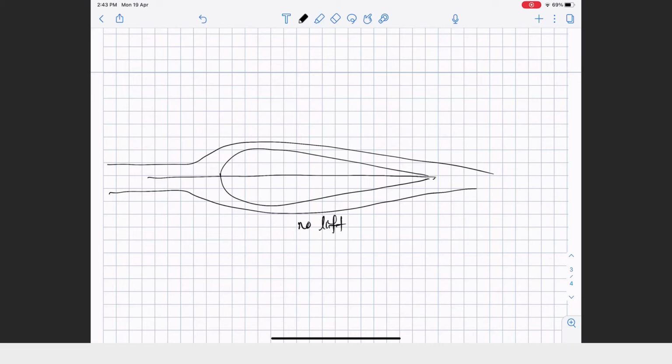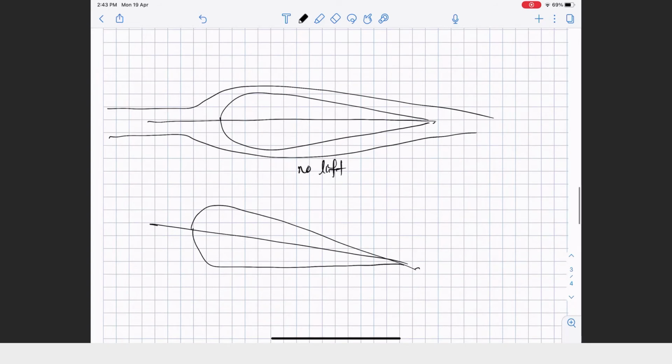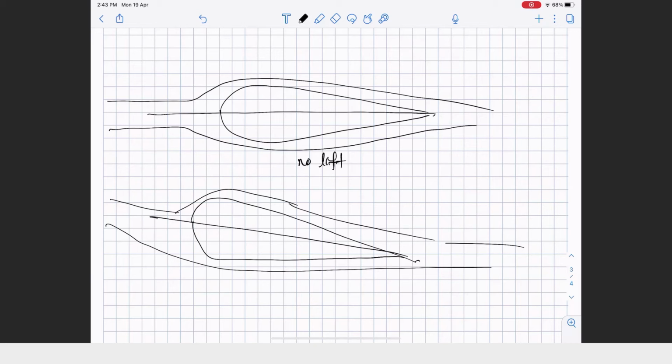It's not so interesting, is it? So what we will do is give the aerofoil an angle of attack. Angle of attack means that now your aerofoil looks something like this. Now I believe you can tell that this aerofoil is generating some kind of lift, because there's a difference between the streamline above and the streamline below the aerofoil. This is when you see the pressure difference between the top surface and the bottom surface.